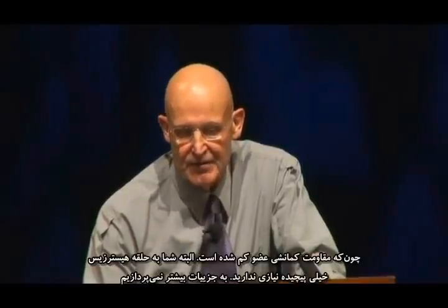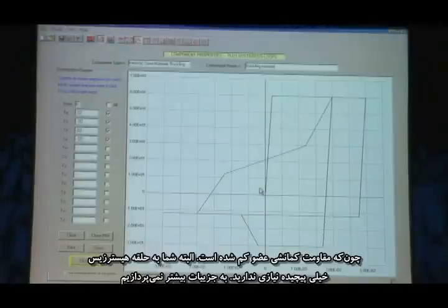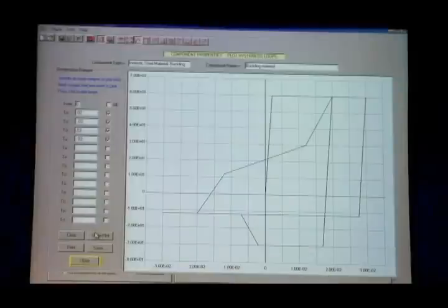And then when it reloads after buckling, it has some different behavior, and when it reverses after buckling, it's lost its buckling strength. It's a somewhat more complicated hysteresis loop, without going into too many details.